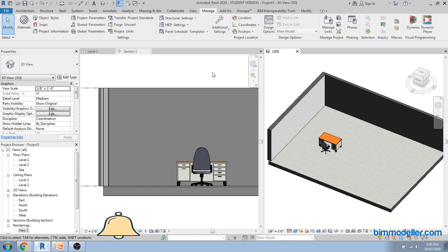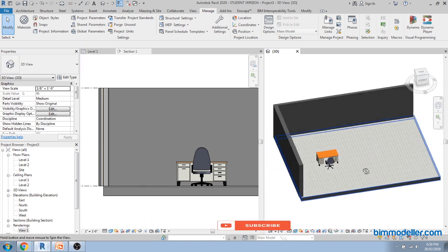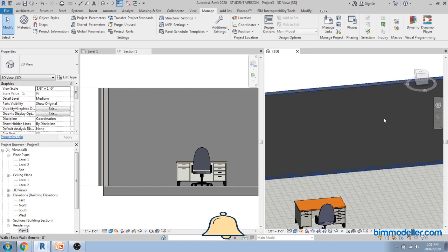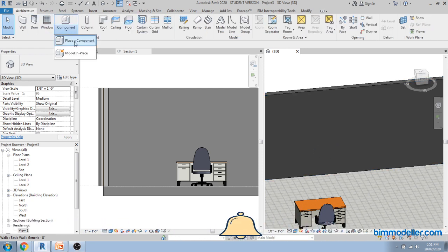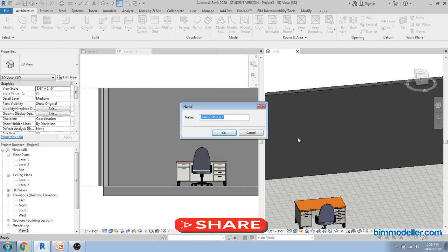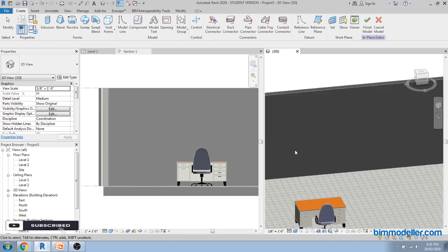We need one more option, a design over in this place, square boxes or maybe a frame. Let's say we create an extrude element in a model in place category. So Component, Model In Place, and it will be the Generic Model. Okay, and say Generic Model 1, enter.